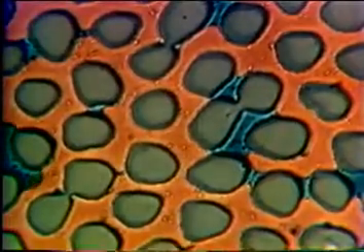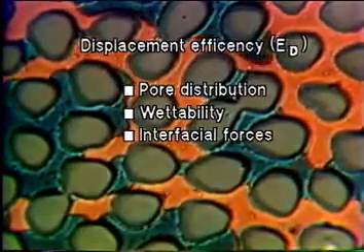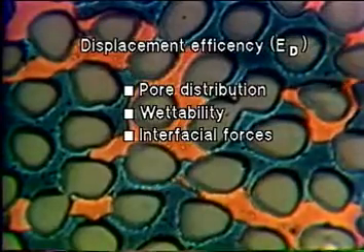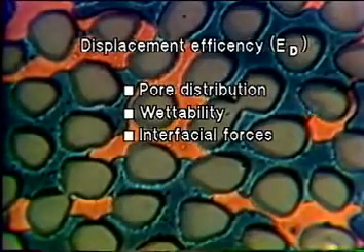But what about displacement efficiency? Isn't it enough just to get the displacing fluid to contact the oil? The simple answer is no. Oil is not displaced in a piston-like manner. As fluids move within a porous medium, the displacement efficiency is determined by the size and nature of the pores, the rock wettability, and the interfacial forces that exist between the fluid phases.